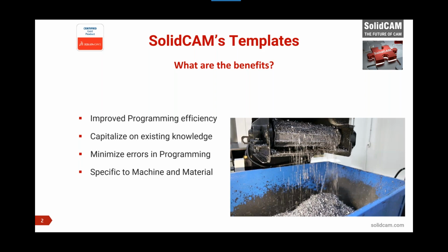Well, SolidCAM's system configuration, what we call SolidCAM settings, includes default templates, okay? And so in SolidCAM settings, you can make these specifically configured to help optimize this idea of running a certain material on a designated machine. Using multiple custom configurations will help the programmer switch from one scheme to another quickly, ensuring that they're working with a system environment that supports the default machine, material, tools, templates, tolerances, all of those things that they want to be running for this particular condition.